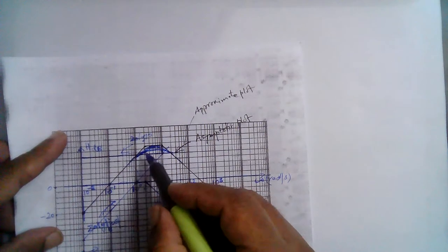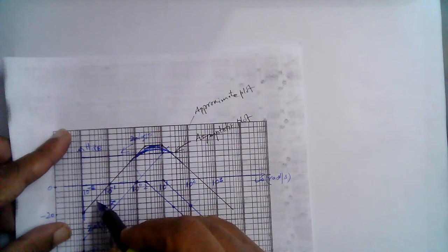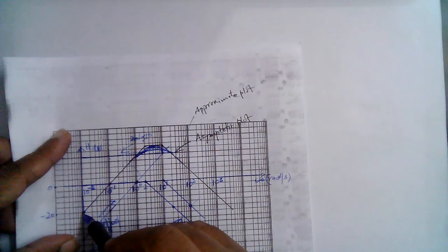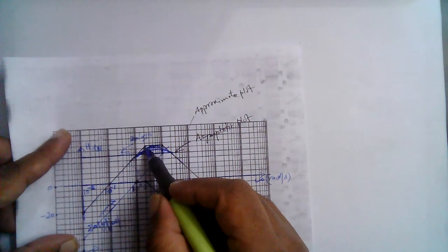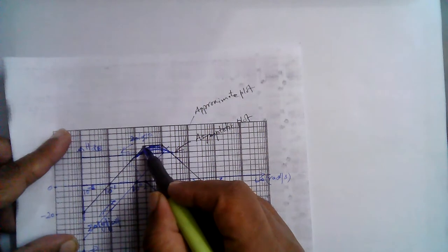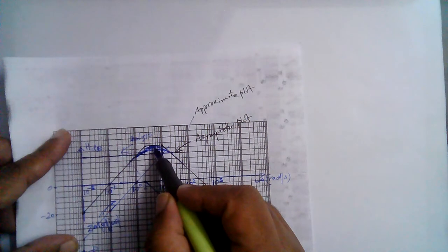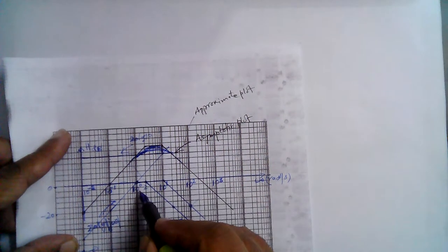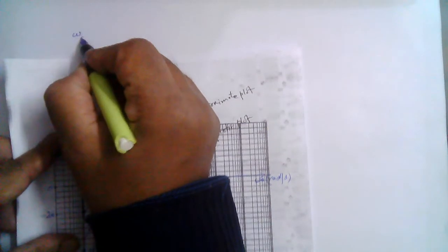So, for example, let's look at this magnitude plot. We have this straight line here, and this straight line goes on from minus 20, crosses 10 power 0, goes on till here, and flattens out here. At this point we have a corner frequency. At the corners where the plot changes its direction, we have a corner frequency. So this is 10 raised to the power 0, this is 1, and this is 2. So we have a corner frequency, omega c1, at 2.